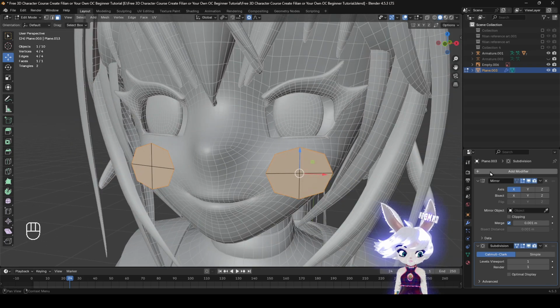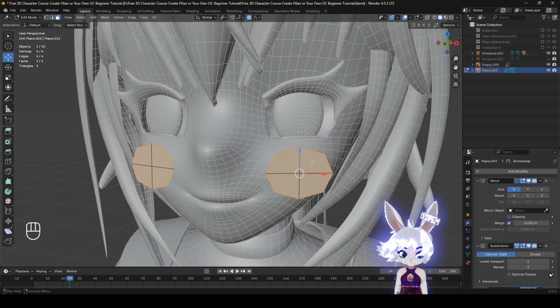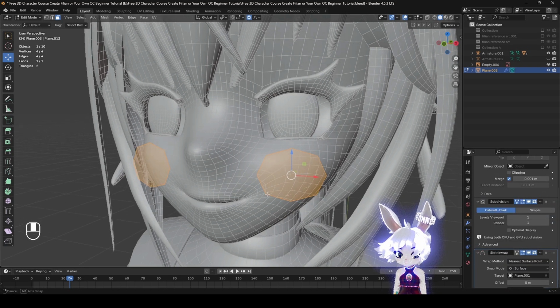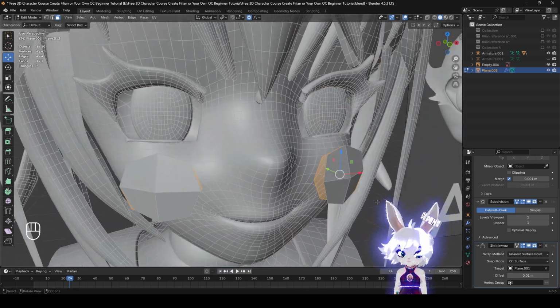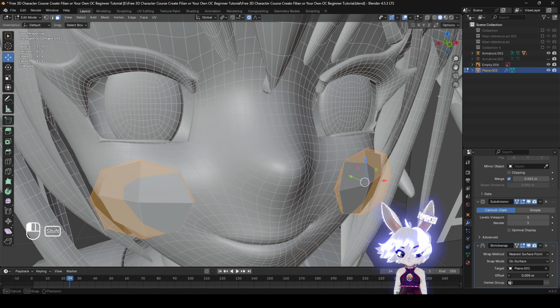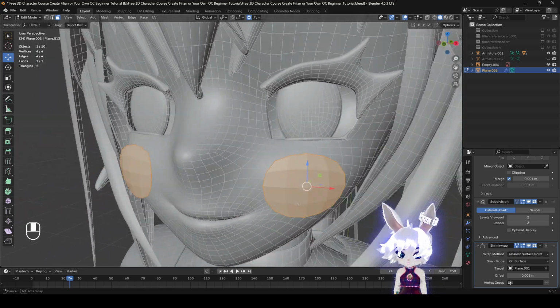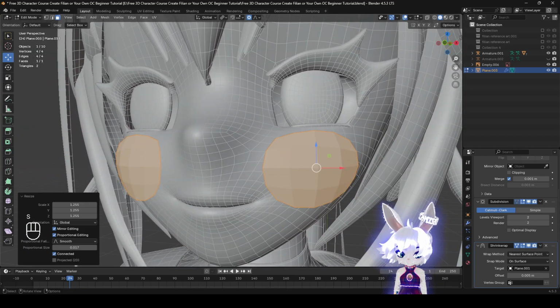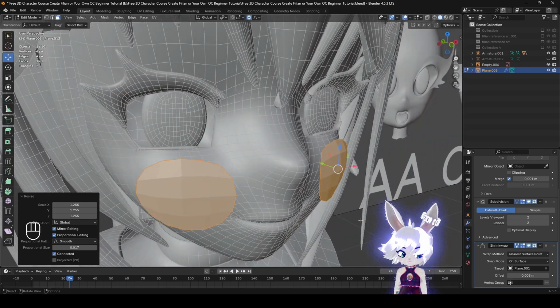So see what's going on, and add deform and shrink wrap, and go down here and select your mesh. Now you see how it's popping off the character. I'm going to shrink it so it's kind of close. I'm going to add another one, like this. See that? You can make a blush mark. I will usually do a texture for that though. You do S to scale. I'll probably do about that big. We don't want it too close because characters talk. It's going to wreck it.